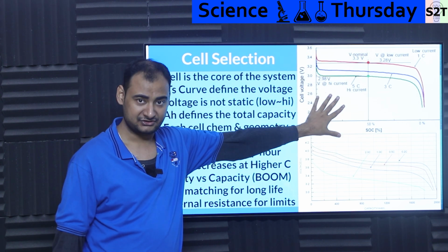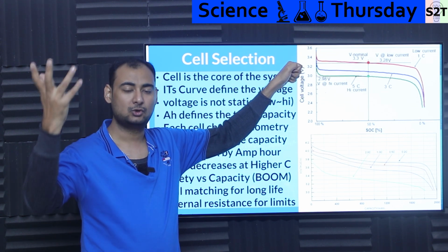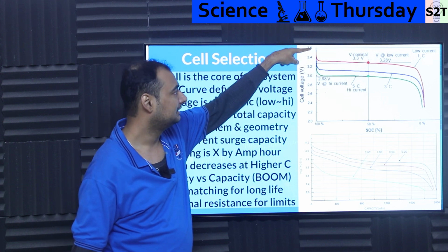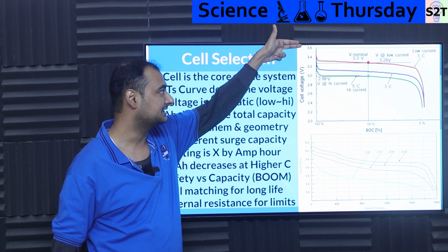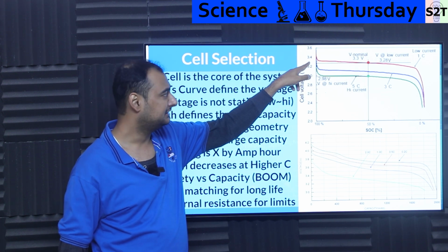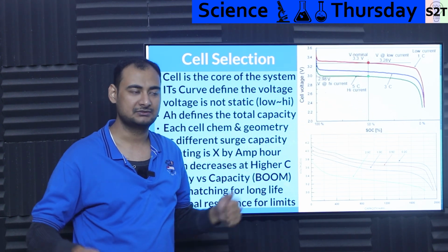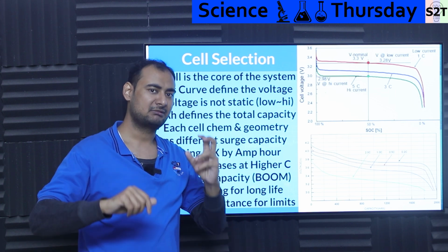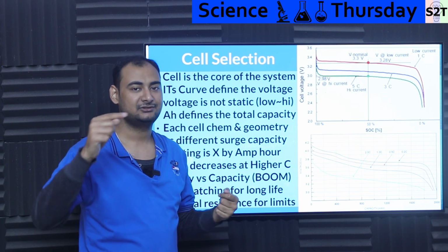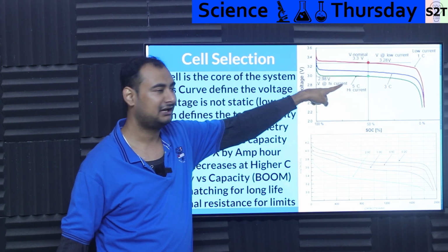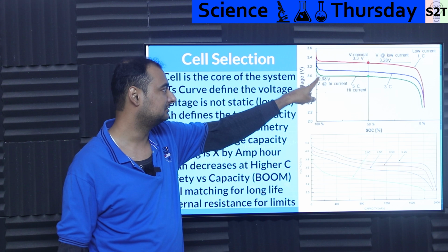For example, same chemistry, same cell, I'm discharging it at 1C. Let's say it's an old power bank that barely charges at 15 watts. With a fully charged battery, I apply a load, and the voltage drops from 3.6 volt to 3.3 volt, and then you have a flattened curve, and then it almost gets depleted at roughly 3.2 volt. Cool, awesome. Same cell chemistry, and now I'm going to apply a power delivery circuit to it. Because you're dumping far more watts, the C rating on the cell goes up. Now you have a C rating of 5, high current. And here's the deal, the moment you turn on your load, it goes from 3.6 volt to 3 volts.